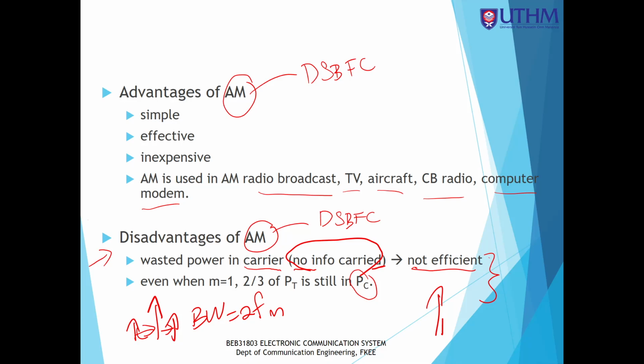You see that sometimes it uses modulation, sometimes it uses modulating, sometimes it uses input signal voltage. Okay, so it is the same thing. So it is Vm. So Vm you can write based on the M. Okay, so Vm is equal to MVC. So this one is 0.75 multiplied with 2000 volt.